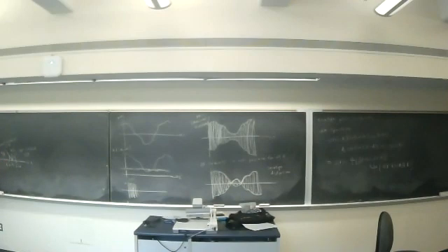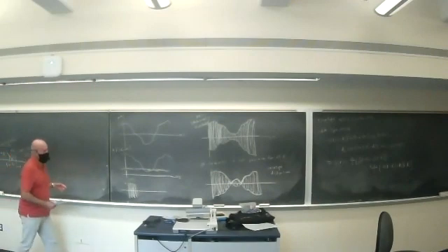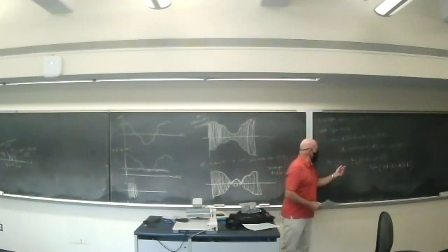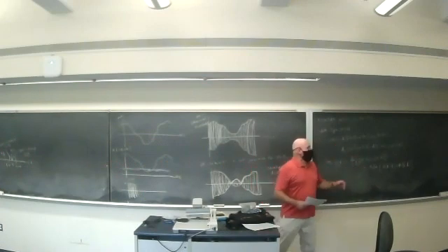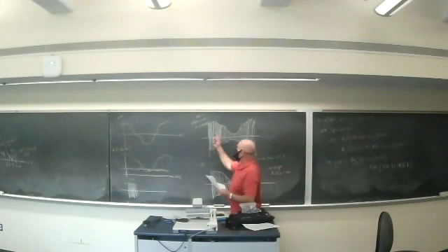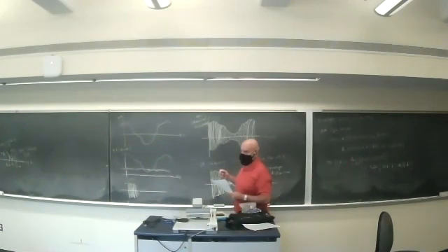It's not called double sideband radio, though, because of the presence of that impulse. That impulse actually is our DC shift, right? That's where that came from. The AC plus the AC times 1 times my cosine gives me those impulses. Those impulses are important because they give me that DC shift that allows me to do envelope detection.